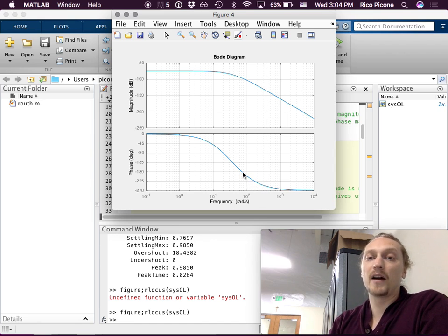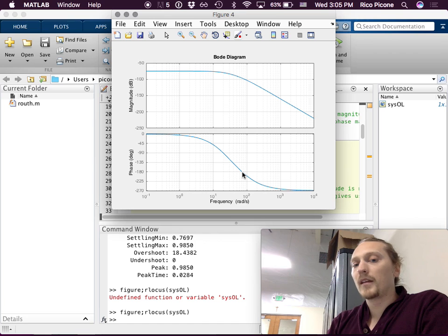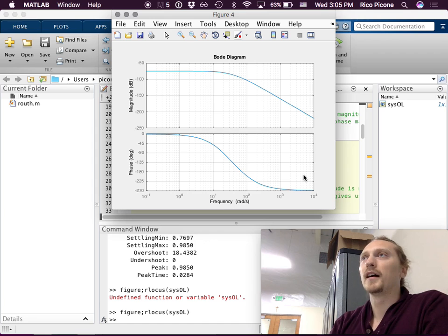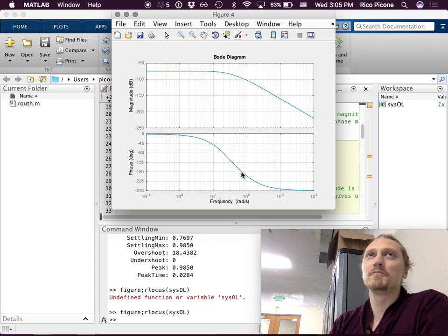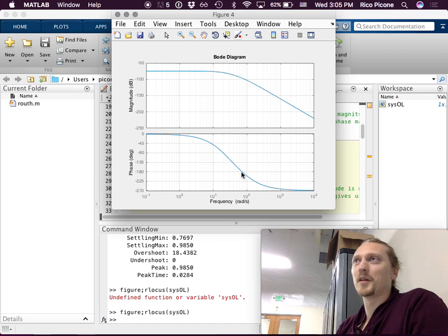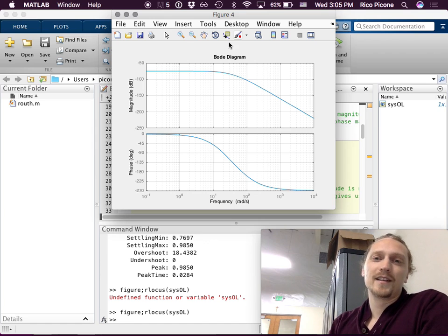And so when you're out here, at frequencies higher than whatever this is, it looks like it's like 80 radians per second or something. At 80 radians per second and higher, if your 0 dB crossing is at that point or higher, you're going to be unstable. So let's see if our little reading of graphs is very good.